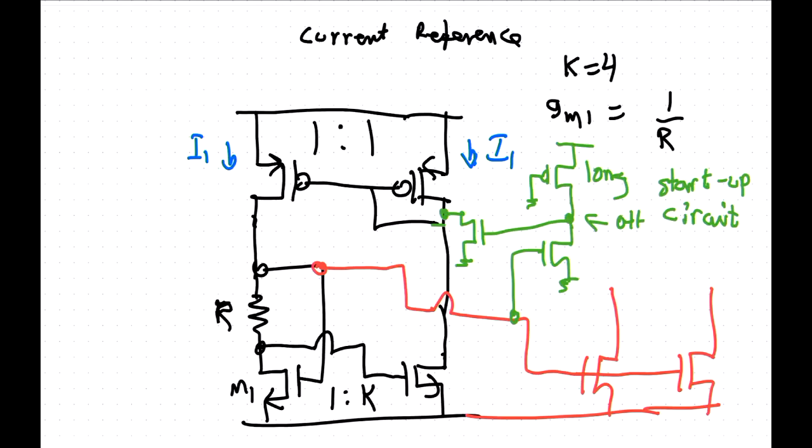So for the same total current, this will be better for speed if you scale up here, but then you have not very much current in the diff pair, which means the noise is poor. But you have a lot of current in the output, which means you can drive a lot of current. In terms of the bias current, if you put most of the current over here, the bias current here is going to be low, which means it is not going to be very good at driving a load capacitance in a slewing condition.